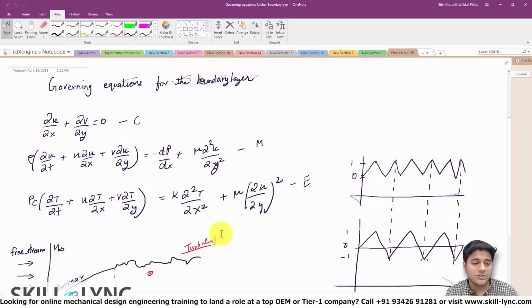So what is the logic that we are going to apply here? Well, we are going to take these governing equations and integrate them over a time that is much larger than the turbulent time scale. So this is called the averaging process. And then we apply something called a Reynolds decomposition, and we convert this original set of equations into a form that is called the Reynolds averaged Navier-Stokes equations. We then use these equations along with the turbulence model to simulate turbulent flows.